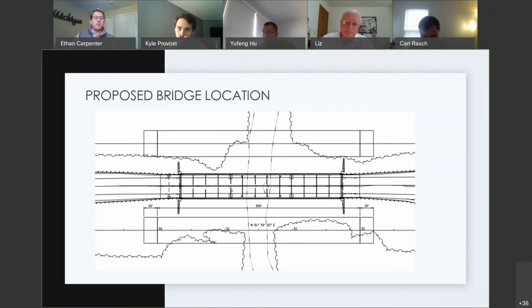The first major design decision was the proposed location for the bridge. We posed three design options and systematically eliminated each design until only one viable choice was present. One option was immediately eliminated, and that was to construct the proposed bridge in the exact position the existing bridge currently stands. This was done because there's no option for a detour route around the current construction limits, so we must locate the new bridge to either the north or the south of the existing bridge to properly maintain traffic.